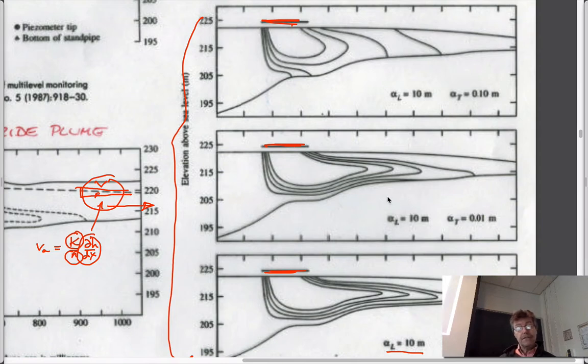If that defines an advective velocity, then we also know that the longitudinal dispersion is a function both of a longitudinal dispersivity coefficient and this advective velocity, and also some magnitude of this effective diffusion part. Because the plume is so definitively lopsided, you might surmise from this that this is big and therefore relatively big and gives this left-hand term a larger influence than this. Otherwise, diffusion would occur equally in all directions. So that's the first clue.